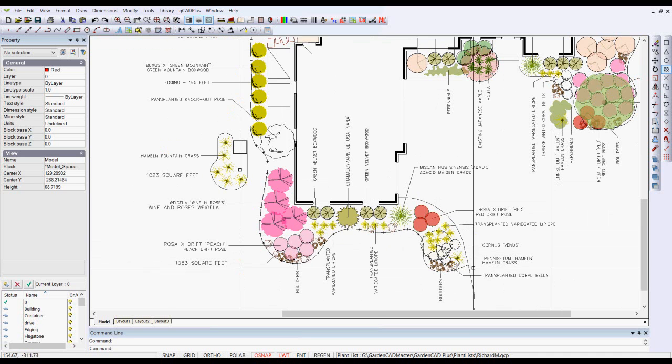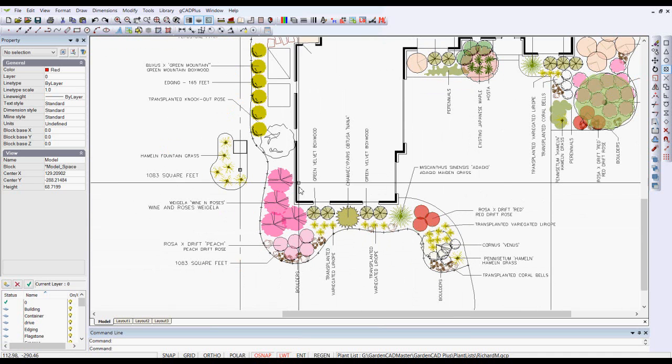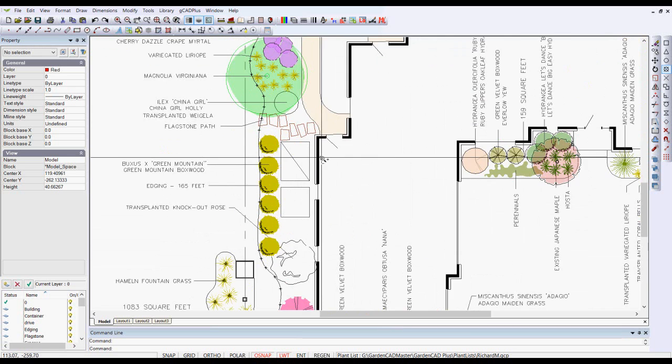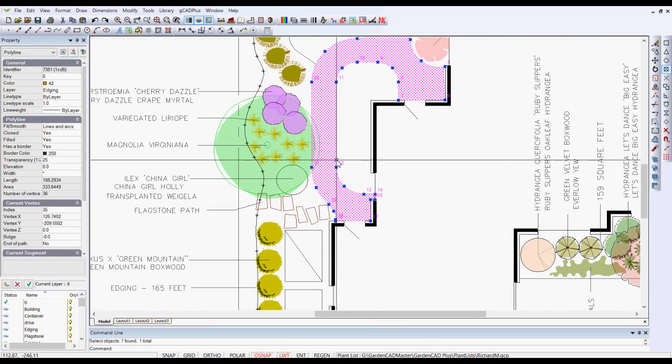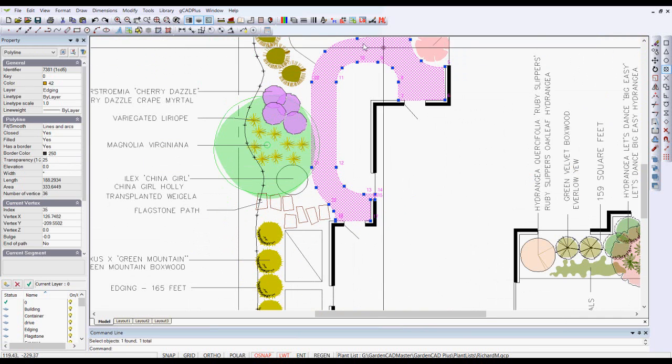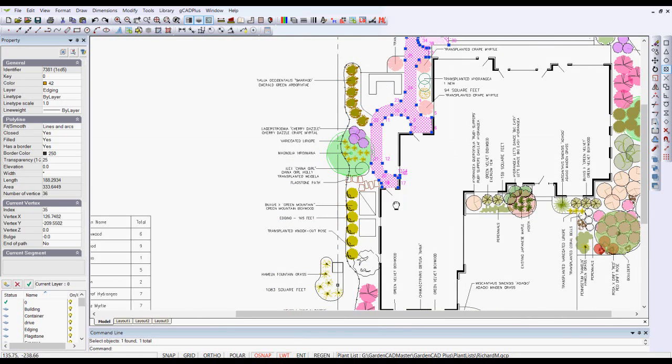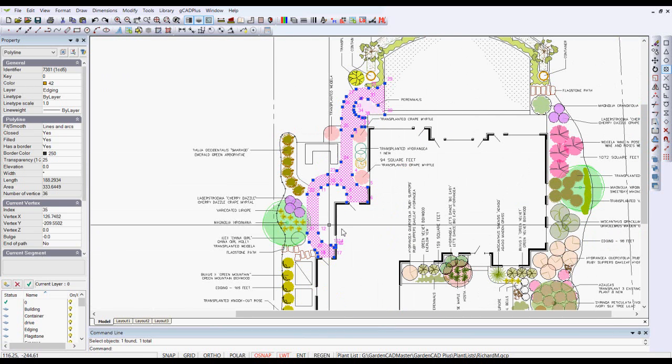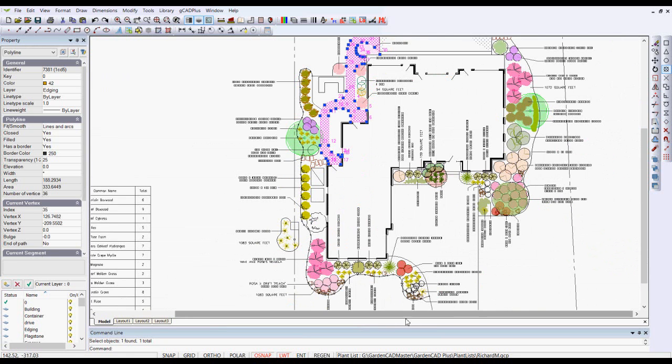It's a comparatively easy job now to draw another polyline around there and work your way around the house to end up with a closed polyline, rather like we've done here for the path at the back of the house that leads into the grassed area at the back here. That's done with a polyline all the way around and then closed, so you could establish a darker background for the planting of the garden beds that run around the extremity of the house in that way.